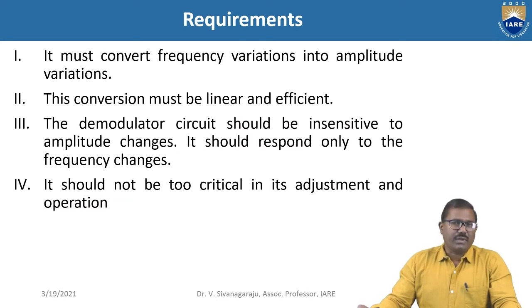So what are the requirements for these demodulators? Any demodulator should fulfill these requirements. The first one is it must convert frequency variations into amplitude variations. And the second one, this conversion must be linear and efficient.